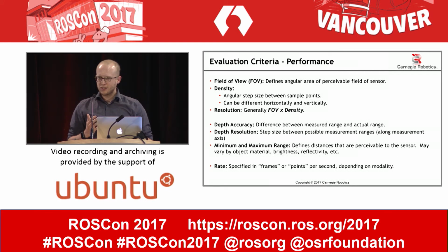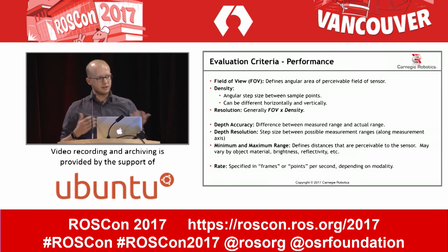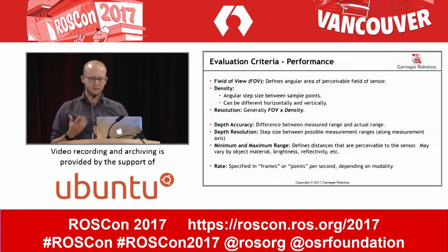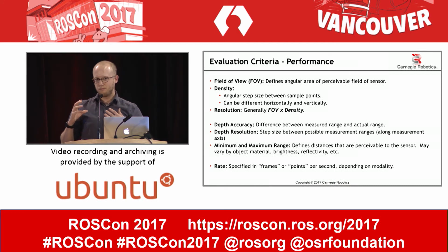So we separate performance criteria into performance criteria and non-performance criteria, and the weighting of all these different criteria changes dramatically based on the platform that your system is running, the kind of application that you're developing for, and the exact use of the 3D sensor that you're trying to select. So the field of view, or the density, or the data rate, or the depth accuracy, or the angular field of view, or the angular density, all of these things may have very different requirements for your application than other people's application. And the importance of each of these is also going to change dramatically by these sort of application-specific factors as well.